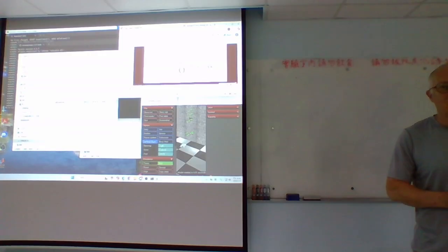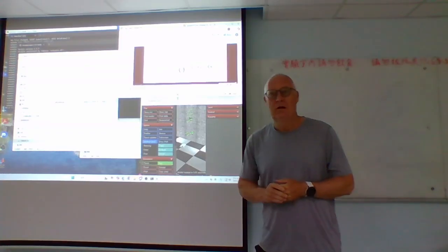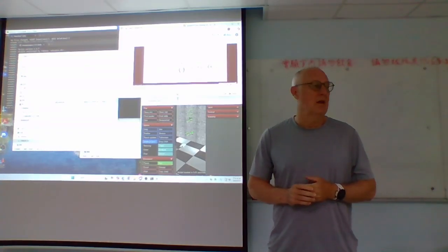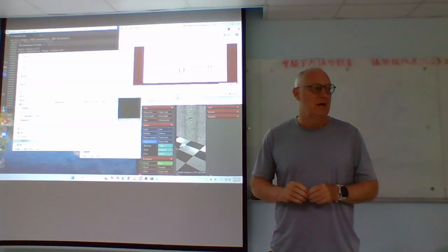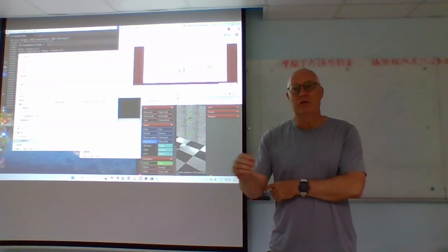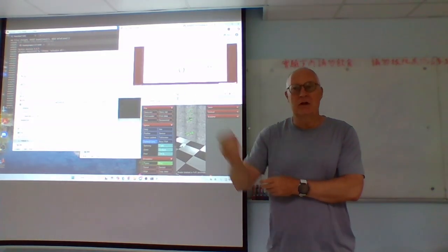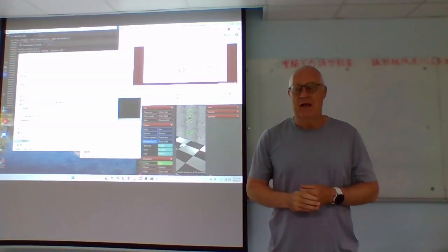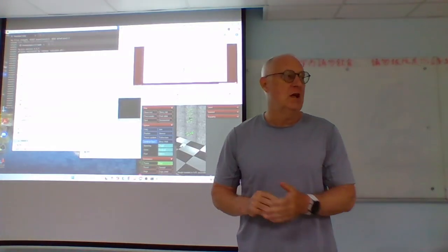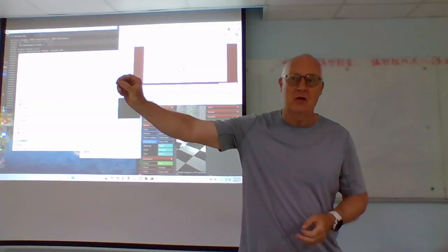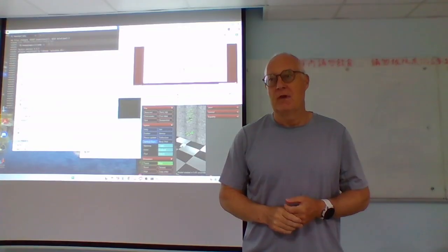The input are joint angles, and the output are Cartesian coordinates. Yeah, that's right. So the input is going to be what's called the joint configuration. If it's a revolute joint, it would be an angle. If it's a linear actuator, it would be a displacement. And the output would be, for some kinematic chain, usually the end effector position in the world coordinate system.